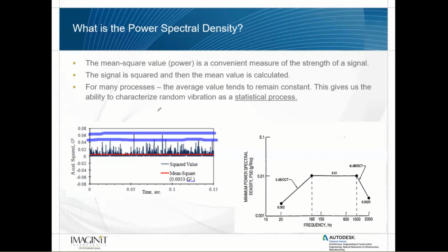And in that frequency band, you may not see very many accelerations. You may only see it hit, let's say, 1 G of acceleration, 5 or 6 times over that entire data range. The likelihood of seeing 1 G of loading is pretty low. However, if you were to look at a frequency from 10 to 20 hertz, the statistical probability of seeing maybe a half G of loading might be significantly higher. So basically, we're building a histogram of our inputs and saying there's a high likelihood that we will see half a G of loading, and there's a very slim likelihood that we'll see 10 Gs of loading.